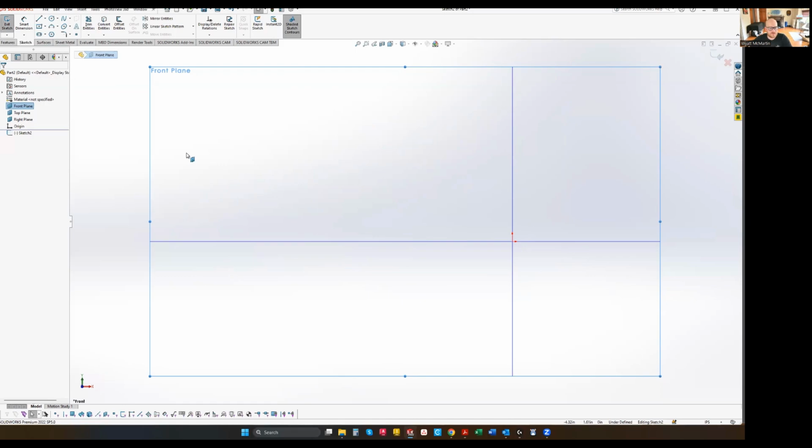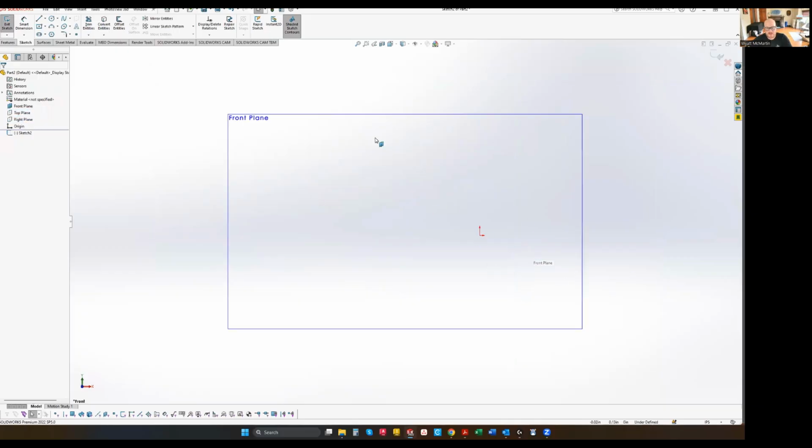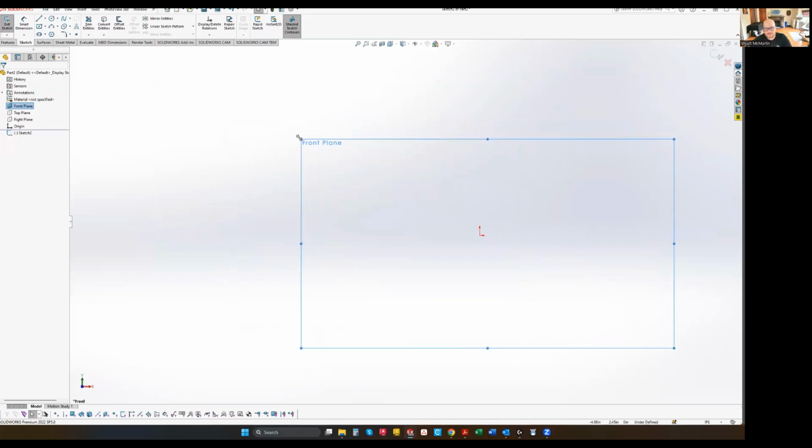So we opened up a sketch on the front plane. I'm going to go ahead and highlight the top and right plane and hide those for now. And it's okay because I drew something in a weird location earlier. Now the plane is not showing as centered. If you click on the plane, you can recenter it. But it's really not an issue, because you don't even need to have this visible. You could just have it invisible. We know we're on the front plane. But since we're all new, I'm going to click show to re-emphasize what we're doing here.